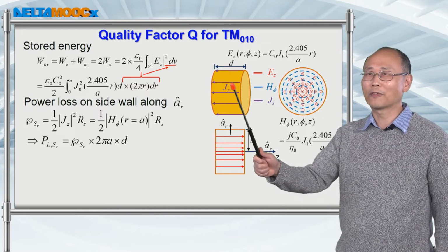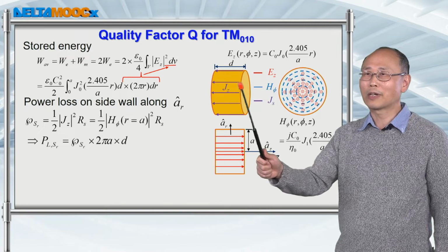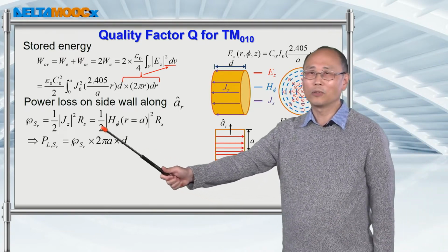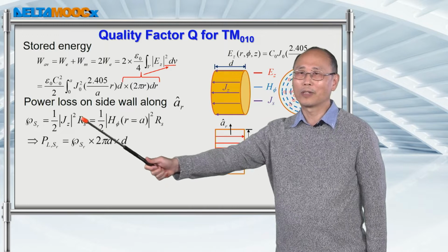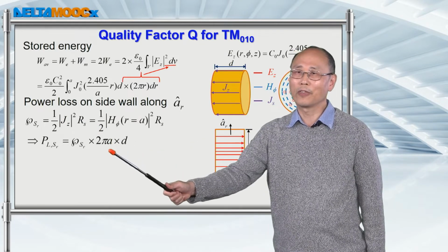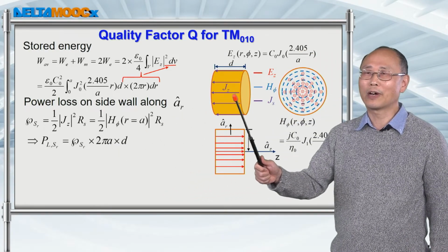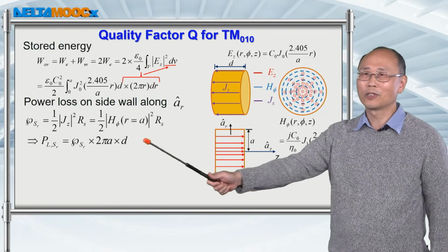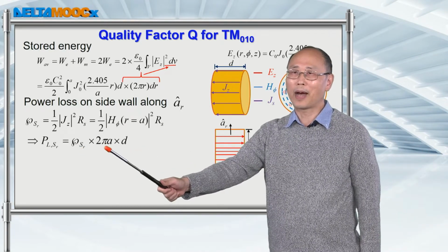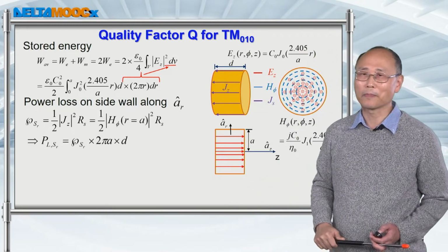So on the surface of this, the R equal to A, it induced the surface current along z direction. So there's still integration of the power loss density over the surface. Turns out that those currents are not function of z. So you can just multiply this loss density by the surface at R equal to A.